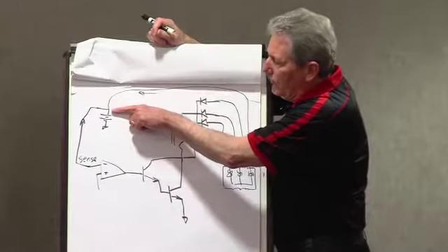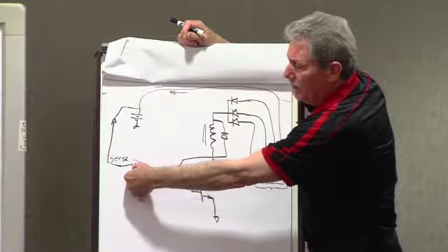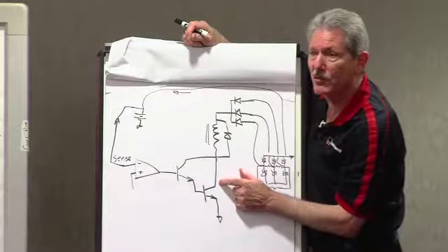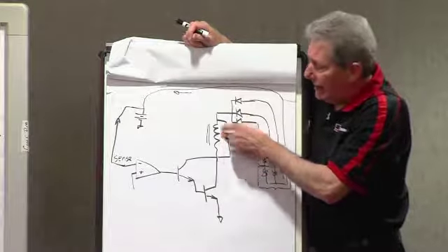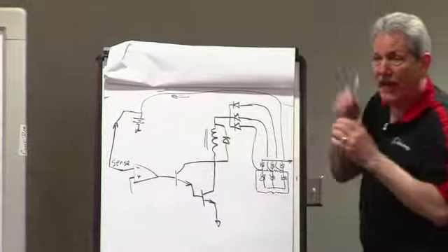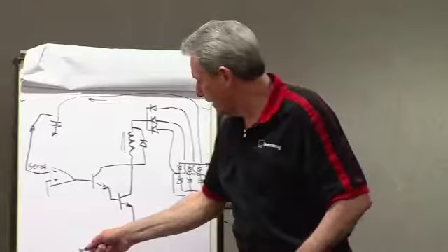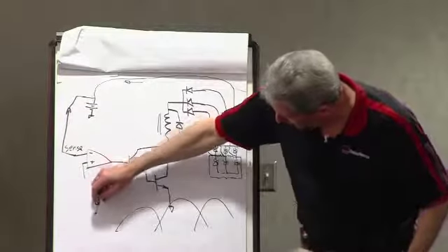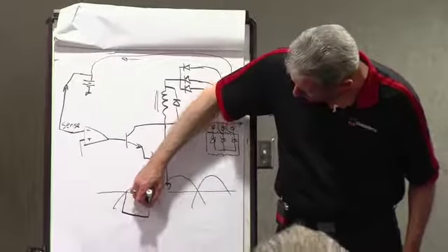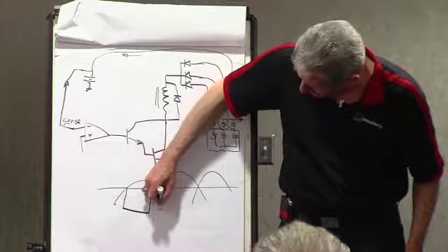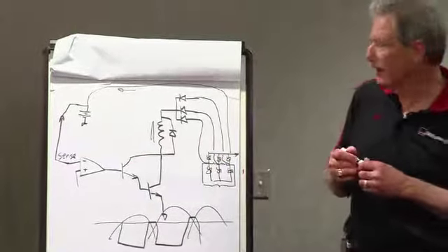So when this voltage gets above the set point, the thermostat temperature, this voltage becomes higher than this one, which opens this switch. When this switch opens, the current decays through this, and as soon as that happens, it's going to drop this voltage. So the output is pop, pop, pop, pop. And if you look at it, it's switching on the ripple here. So here's the set point voltage. When I'm above, it turns the output off, on, off, on, off. So it's a real simple regulator.